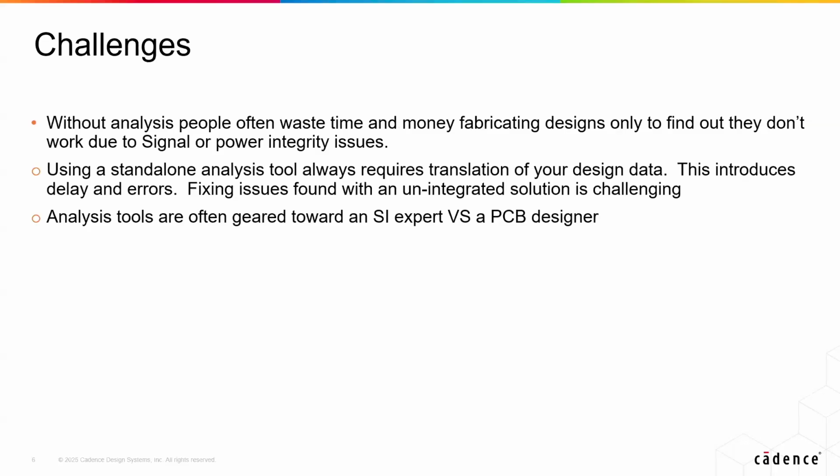If you're not doing analysis of your design, you've experienced it once for sure, and if not, you're going to, where you build a design and it doesn't work. And now you're looking at spending even more time and money because you're either having to debug the problem that didn't work and then rework it. So now instead of working on your next product or project, you've taken engineers and PCB designers offline to debug a problem. You've wasted money fabricating it. You got to get back in line with the fabrication queue. All bad news all across the board. So that's why you want to take the time to do signal and power integrity analysis on your design.